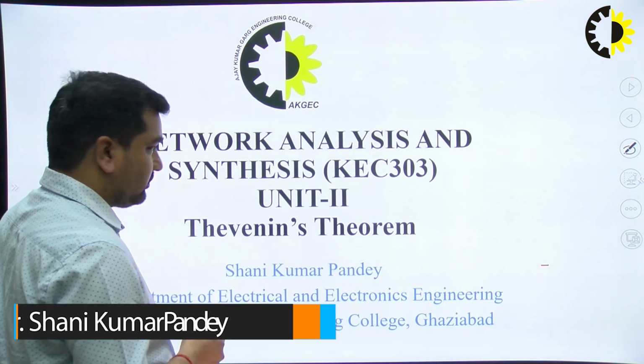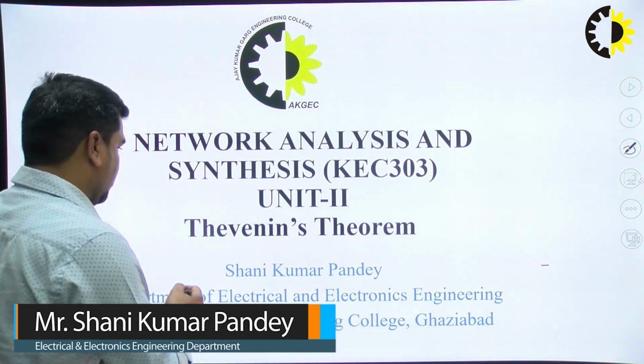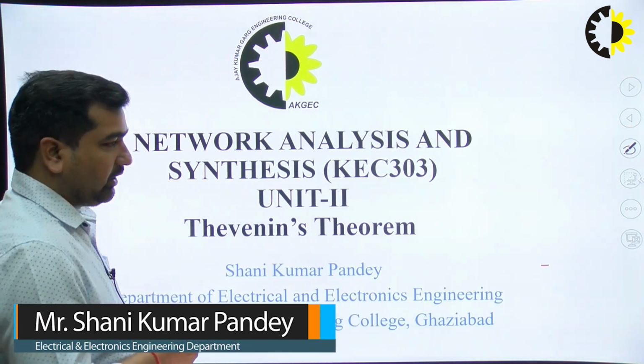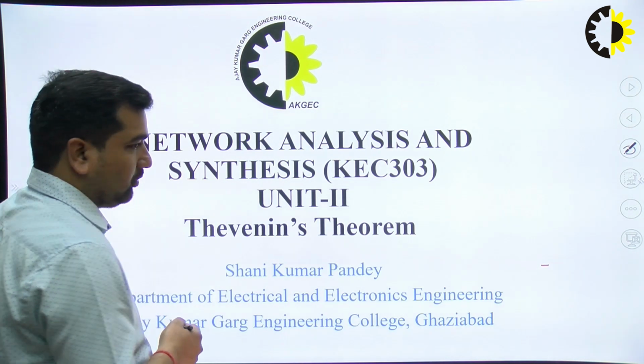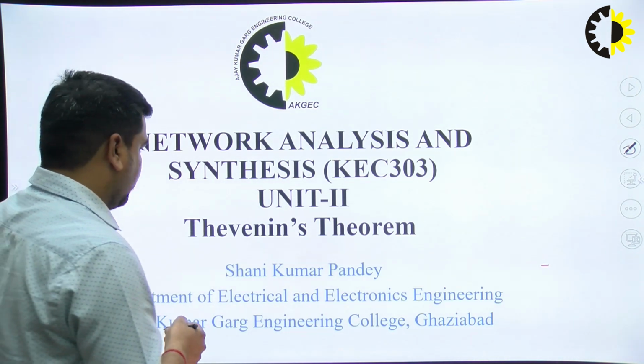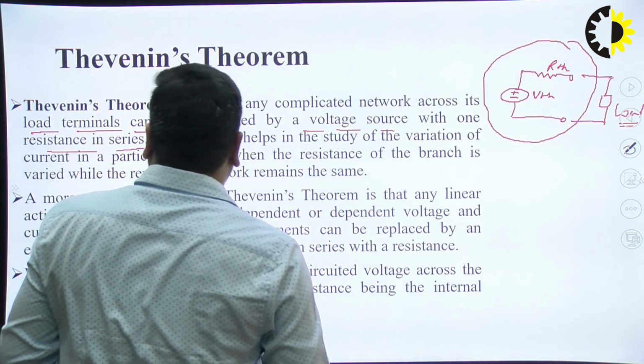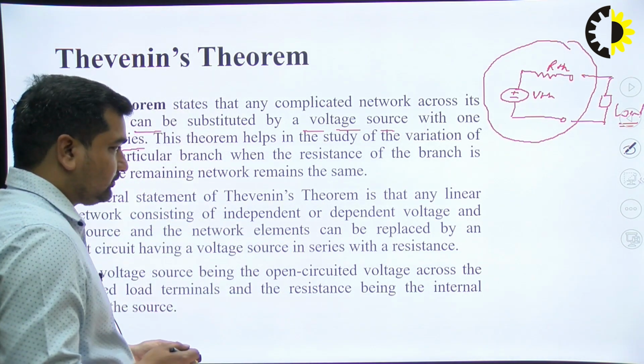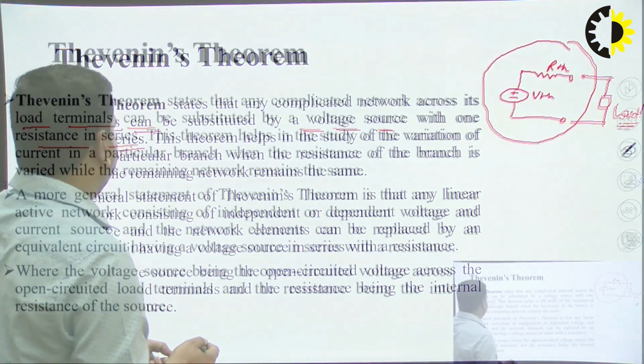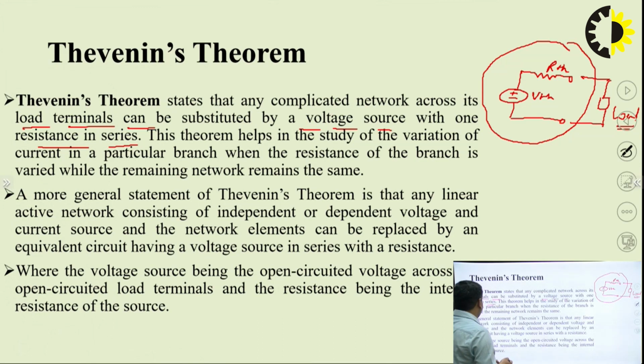Today we are going to discuss Thevenin's theorem, how we apply Thevenin's theorem to different problems of electrical and electronic circuits. So let's start with the statement of Thevenin's theorem. Thevenin's theorem states that any complicated network across its load terminals can be substituted by a voltage source with one resistance in series.